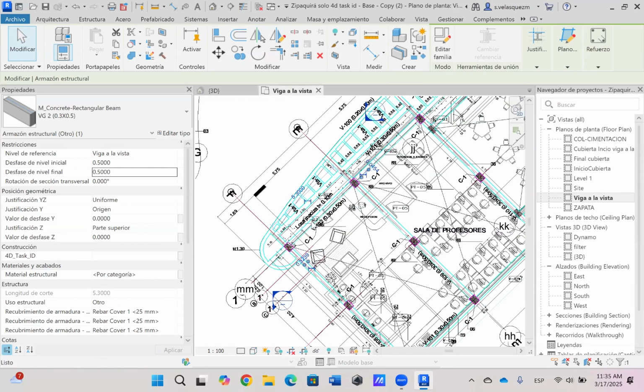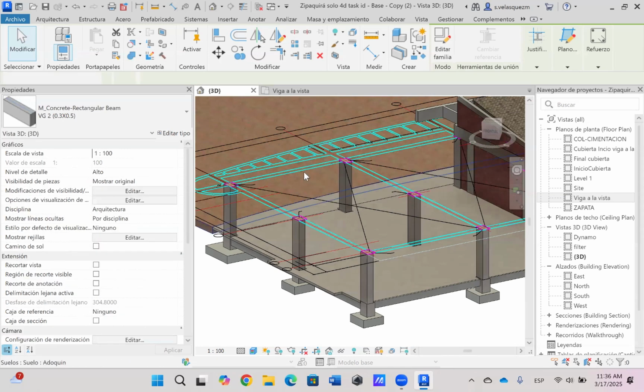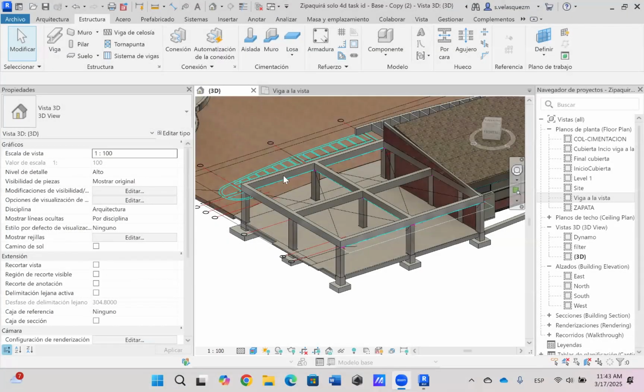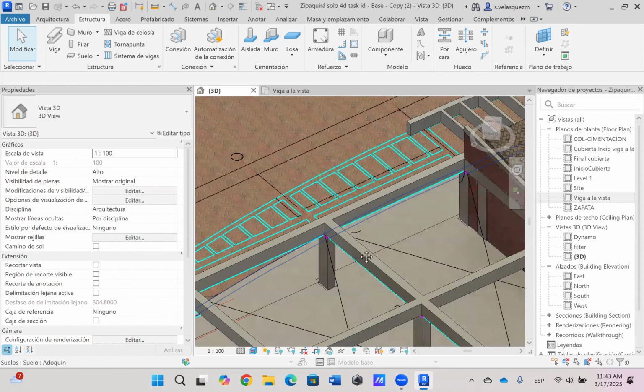Now go back to the exposed beam view and preferably delete the previously placed beam. With the correct modeling conditions in mind, place the beam again properly. Once you've finished modeling all the overhead beams, they should appear directly on top of their respective columns, with no gaps between beams and proper intersections where needed.